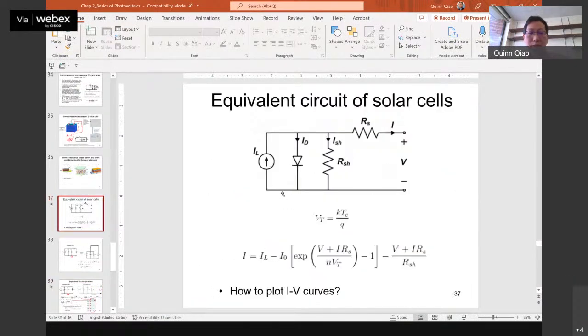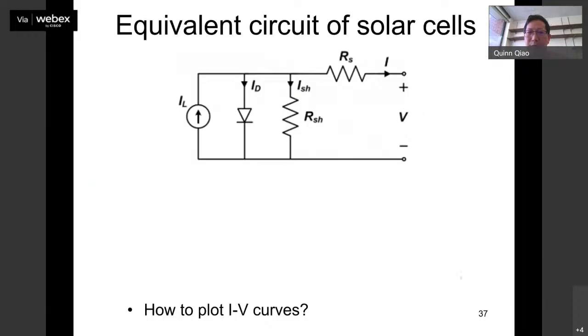Okay, you see the slides here. Can you guys see the slides? Yes, sir. Okay, you see this one is photocurrent, right? This is photocurrent, right? See, under dark, this is gone, right? There's nothing here, right? So the bias here only flows through what? The diode, right? You see that? So in the dark, you have to add bias, right? Because there's no photocurrent, there's no photovoltaic, right? The photovoltaic is also gone. Everything comes from the bias added, right? That's basically a diode, right? So in dark it is real bias, right?